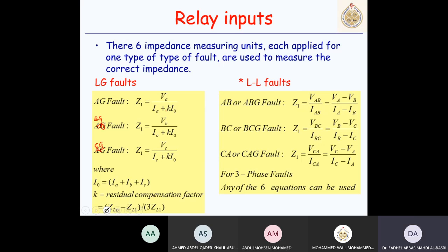Or sometimes the constant here will be without the 3, just to reduce computation, and we just sum here without multiplication, because the constant is evaluated one time and sits inside the relay. While the relay always computes summations at each instant in time and checks whether the impedance has fallen below its measured Z1 and checks it with the zone 1 reach. If it falls within zone 1, then it declares an A to ground fault.